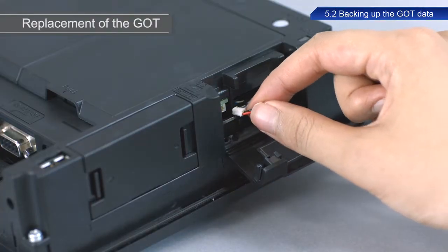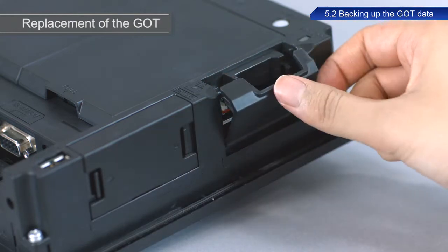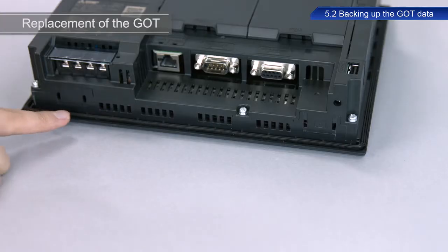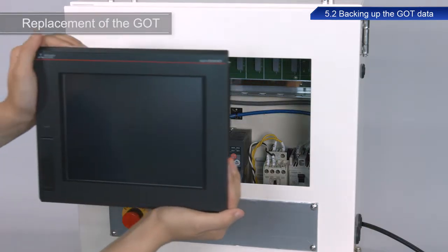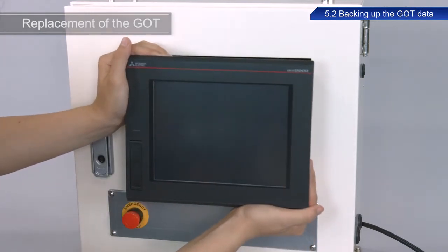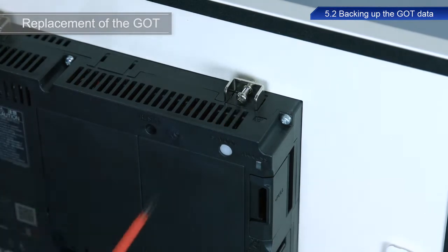Next, we will prepare a new GOT. Connect the battery connector to the device. The battery is not connected at the factory to conserve the battery charge. Next, make sure the gasket is installed around the rear edge of the GOT. Insert the GOT device into the opening. Secure the brackets from the rear side.